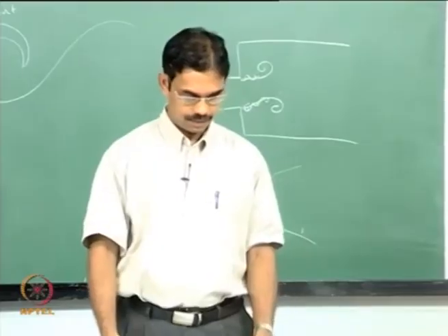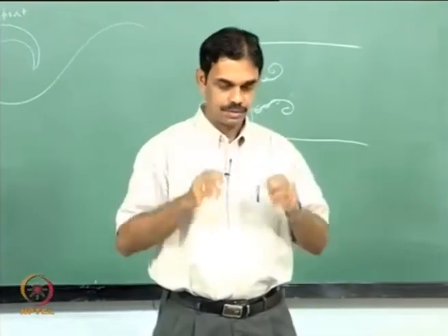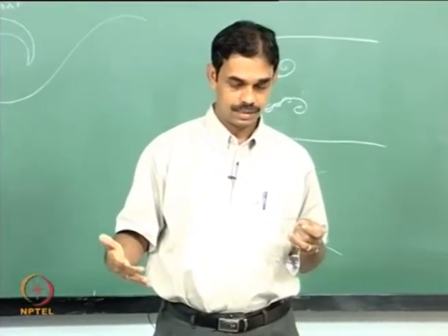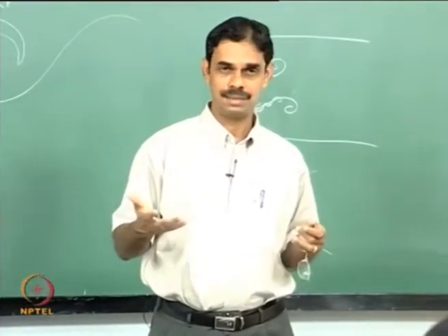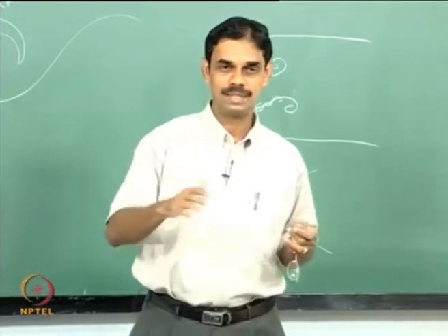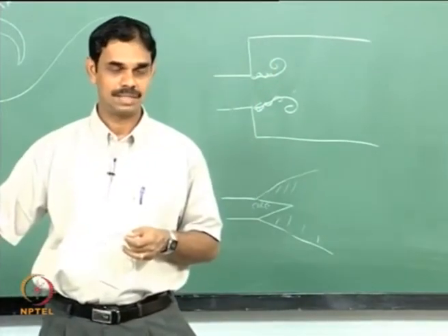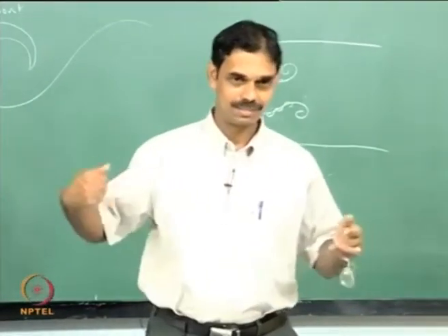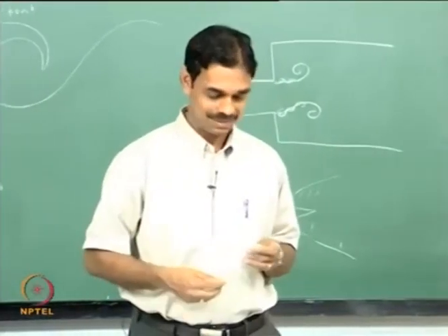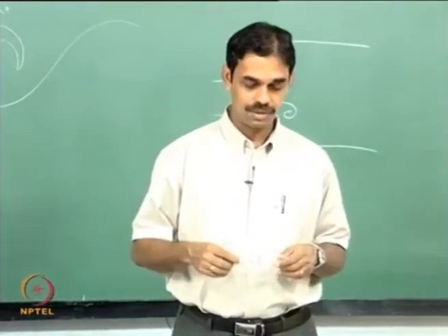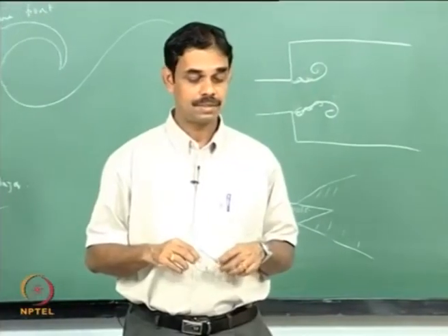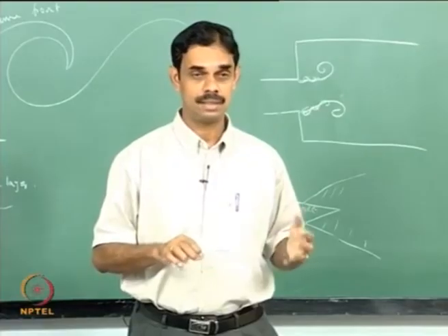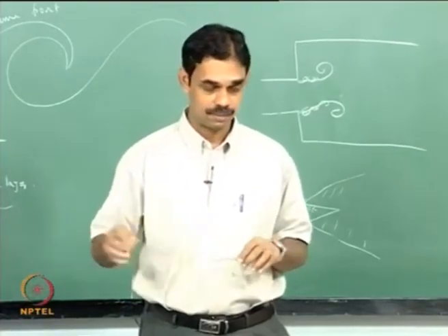So you have the developing vortex go downstream of the dump and impinge against the wall, and again impinge is a very crude term. It's like one shear layer interacting with, when it comes close to the wall, there is a boundary layer there and it's interacting with that. So impinge doesn't mean it just goes and bang hits. Since the downward velocity of the vortex is large, a vigorous mixing occurs between the remaining unburned reactants and the combustion product, again leading to a sudden heat release as this mixture approaches the wall.